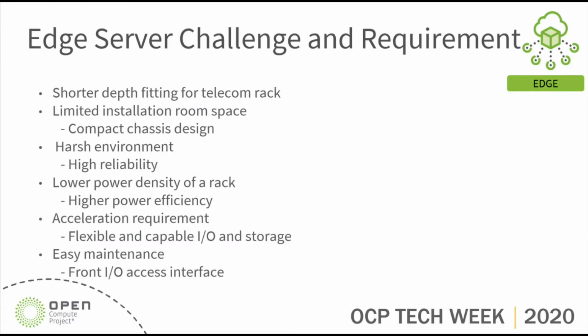Okay, let's go to topic one, the Edge server challenges and requirements. So as we know, the server market is going to deploy from the data center side to the edge side. But on the edge side, there are some challenges for the deployment. The first challenge is that the server design should be short depth. This is for fitting into the telecom rack. Generally, the telecom rack will be 600 millimeters in depth.